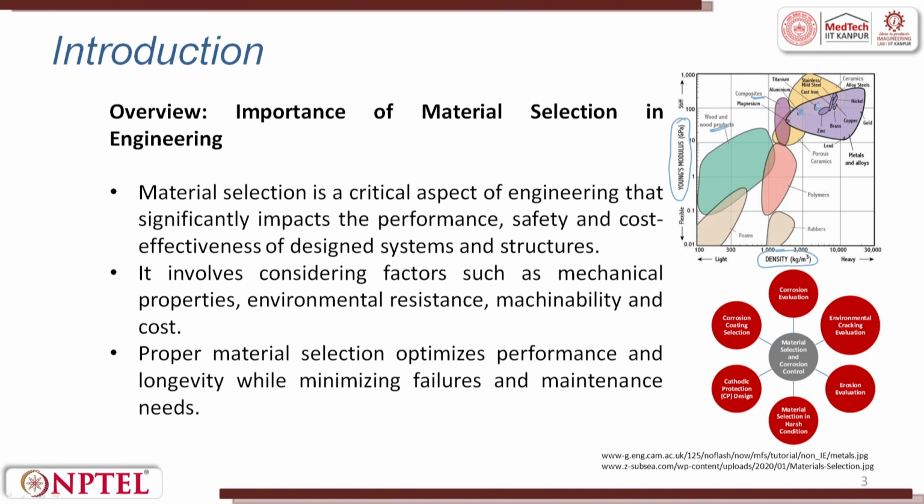Then titanium. Titanium is also lighter compared to metals, that means to say iron materials, mild steel, stainless steel, it is lesser in density. So, now we are trying to explore these possibilities. Looking into application, for example, with respect to Young's modulus, you see there is not much of compromise you do if you choose titanium as against magnesium. Now, you have to take a call whether which one is good, keeping cost, that is primary.